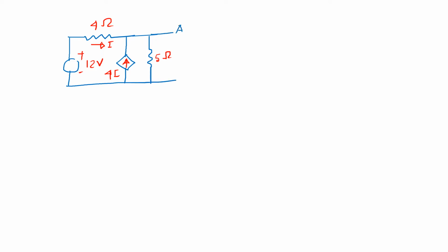So the problem is like that. You have to find out the equivalent circuit across the terminal A and B. So for the solution, first you convert this current source to an equivalent voltage source.